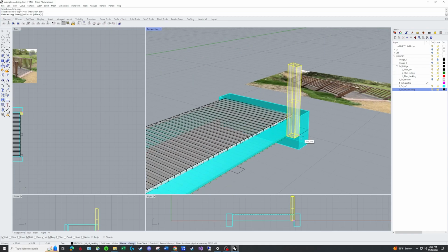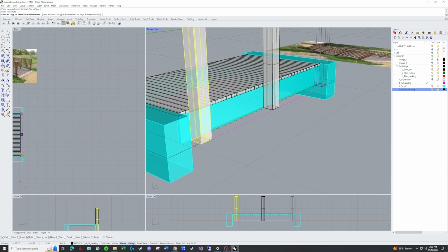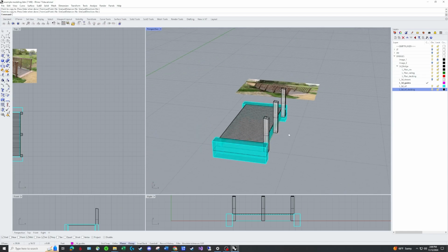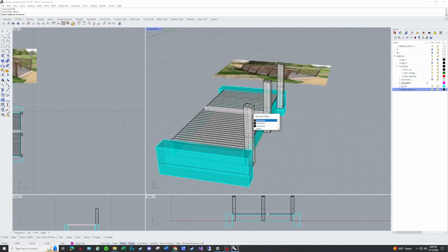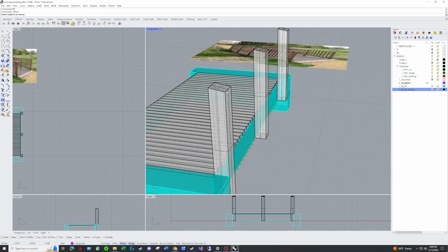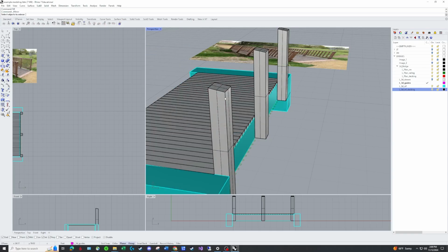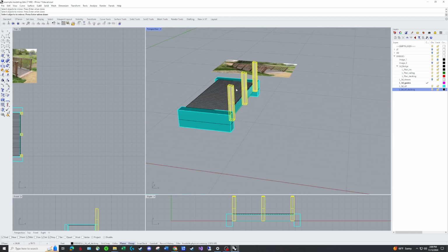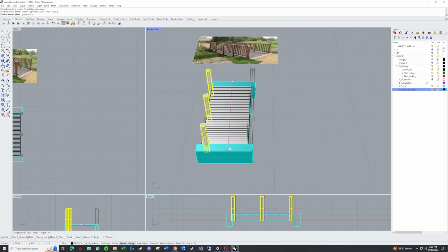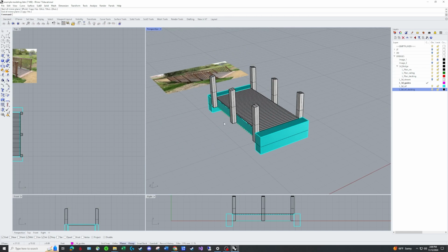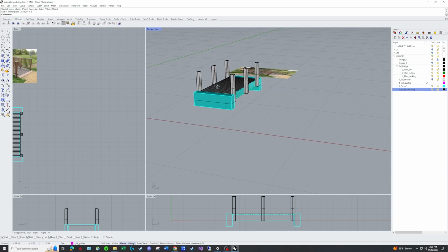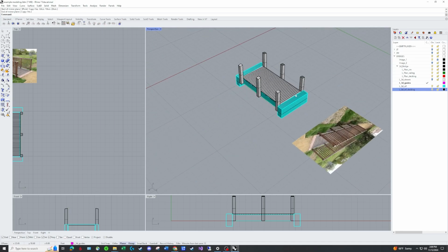So I'm going to copy this, and because I need this to be angled outwards, I'm going to have to mirror this. And you see how when I'm seeing through all that, it's a bit of a pain, so just go to shaded, midpoint to perpendicular, and it should line up. If your drafting is good, it should line up perfectly. And now